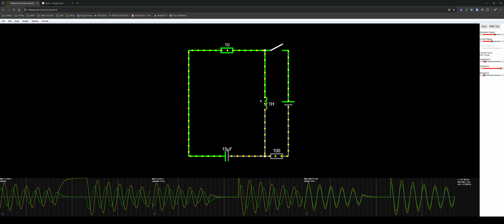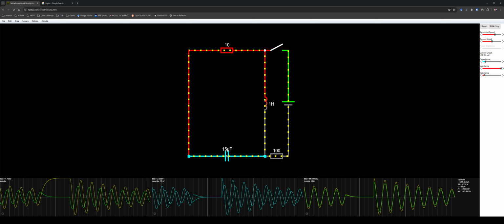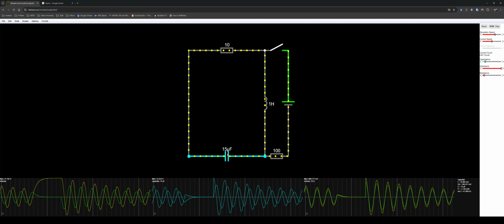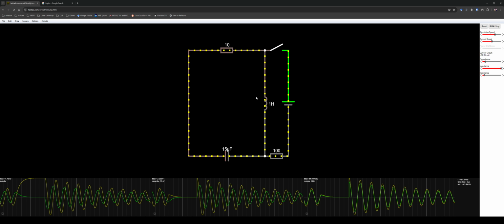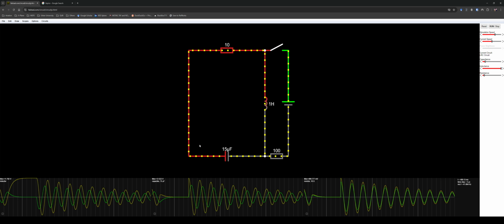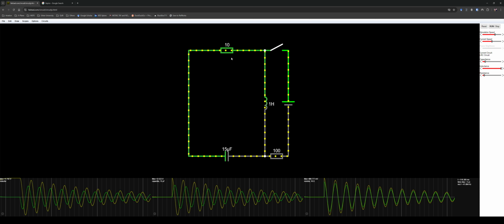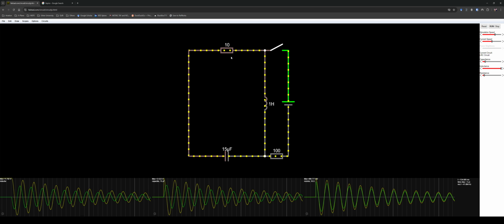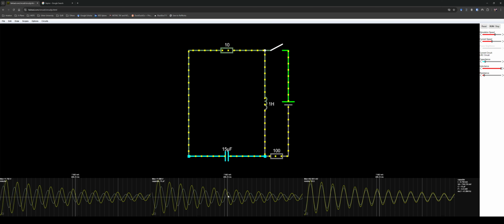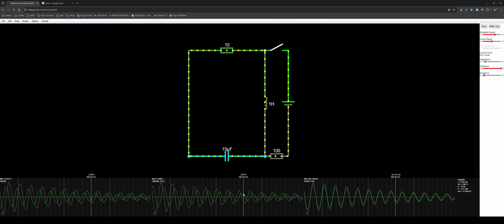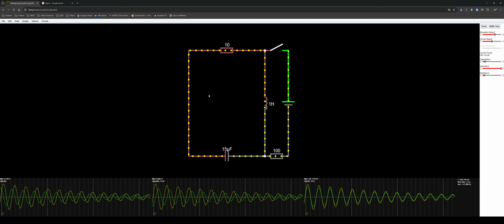Just know that you already know an inductor stores magnetic energy, and a capacitor stores electric energy. So the moment nothing supplies energy to them, they're going to release that energy. And you can see here, as we have a resistor, the resistor heats up with the current, converting electric energy into thermal energy, and you see the voltage in green decreasing with time, and the current in yellow also decreasing with time because they're proportional.